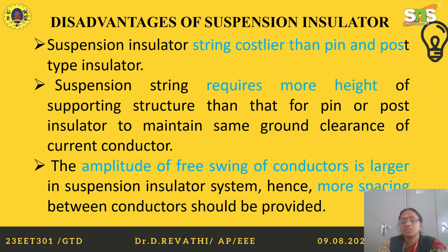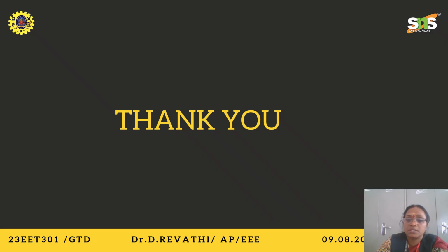And the disadvantages, here I listed a few points. The string is costlier than the pin post insulator, suspension type requires more height, and the amplitude of free swing of the conductor is larger in a suspension insulator system, hence more spacing between the conductors should be provided. So these are the advantages and disadvantages.